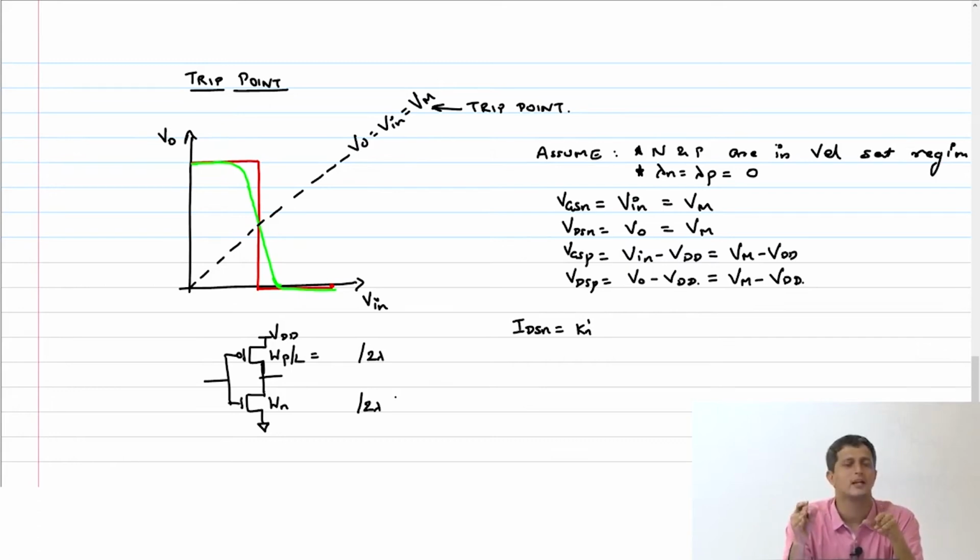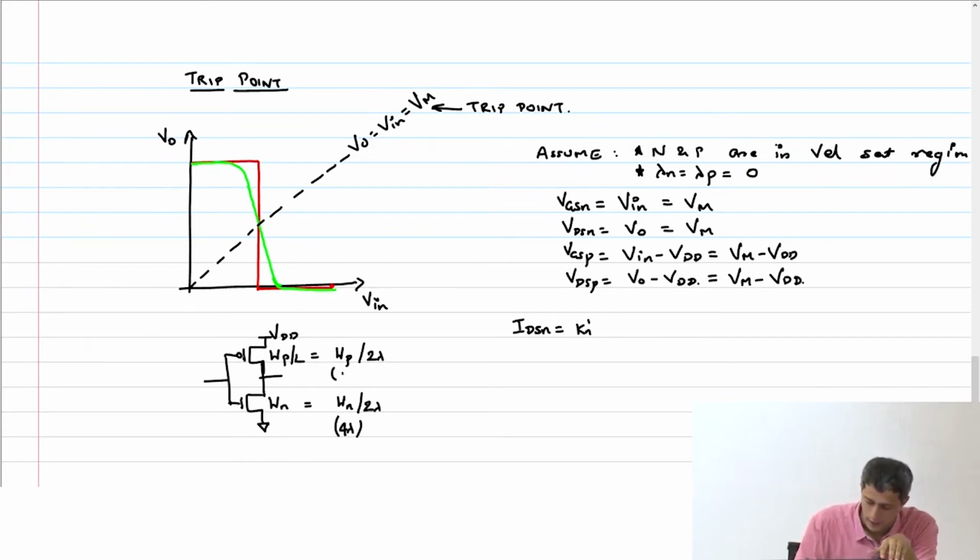Okay, the reason is this scaling sort of worked very well in older technologies. Everything was represented just in terms of this technology length parameter. All design rules, everything that worked well at that time, doesn't work anymore. But for historic reasons, you just need to be aware of this. Okay, so length is 2 lambda. WP is something I don't know. I will have to fix it. This is WN. Typically, this will be 4 lambda and this will be 8 lambda.